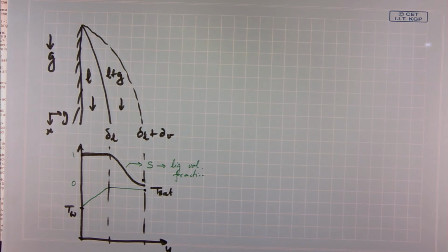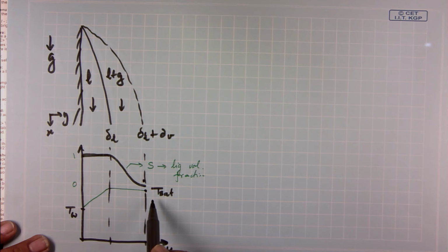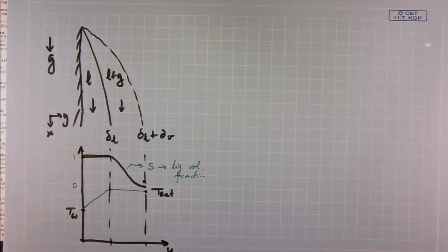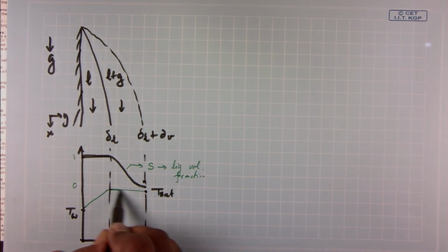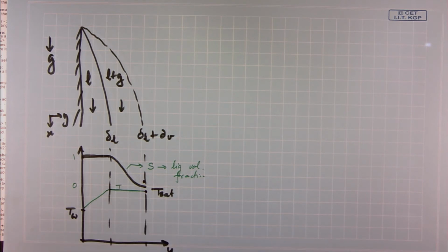So, whatever is condensing on the solid phase, that is what is going out from the surface over here due to capillary action, and that is more or less at the saturation temperature because it is in equilibrium with the gaseous phase. This is an approximation, by the way. Of course, there will be some difference, there will be a little bit of a gradient here, clear. So, this is temperature. Finally, if we were to plot velocity of the liquid, how will it go?